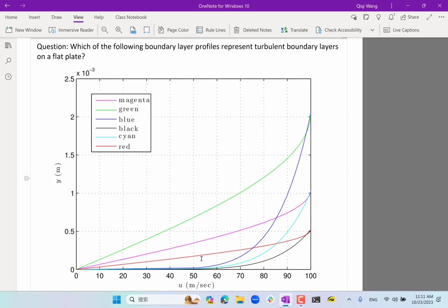Except for in the extremely thin layer close to the wall, which we call the laminar sublayer, the vorticity is never uniformly distributed. The vorticity is always going to be smaller and smaller as you get further and further away from the wall, right? And it is extremely concentrated in a very small region near the wall. All right. Any questions on this?